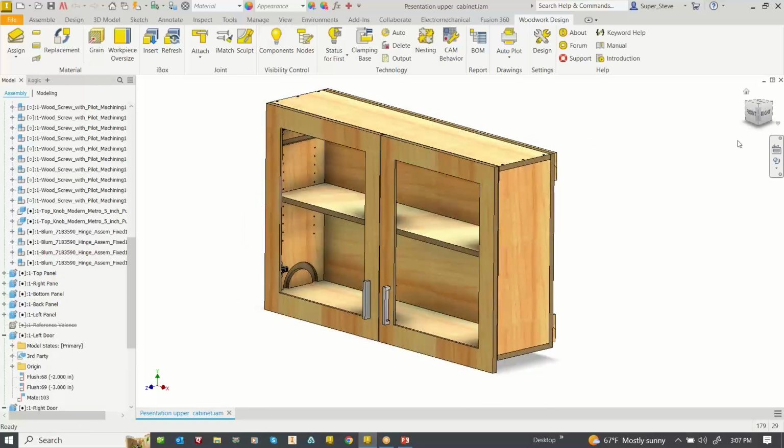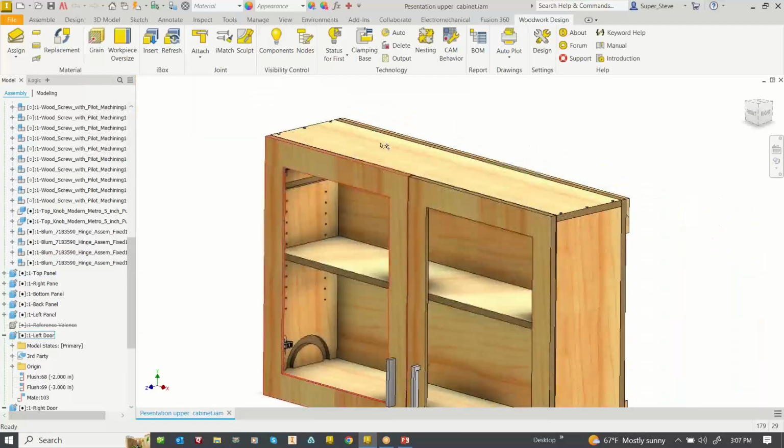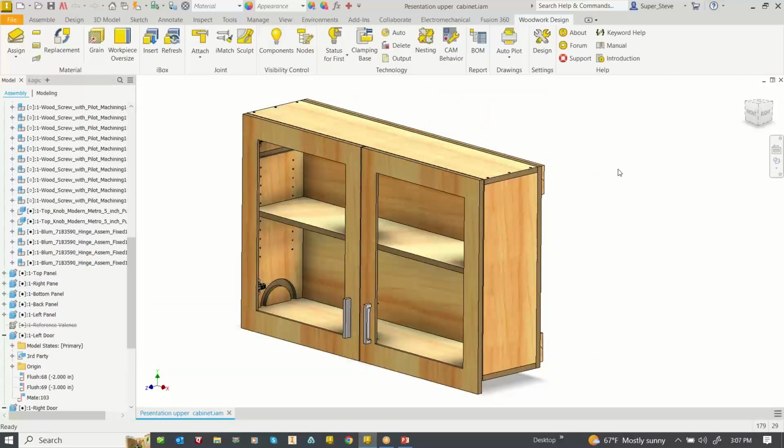Okay, so our tool segregates this in two ways. First, like materials and like thicknesses get nested on the same sheets. So if I have, this is all maple on MDF. Everything here is maple on MDF. So this would all be nested on single sheets. But if the doors were made out of something else, they would be nested on a different sheet. Makes sense? Or if the framework or the carcass had two different thicknesses, they would be on different sheets. So all of these things assist us in verifying our model also. We think everything's 3/4, but then we find out later that the interior dimensions of those shelves were not 3/4, they were 19 millimeters. So they're not going to be right. Or the joints are not going to be right.